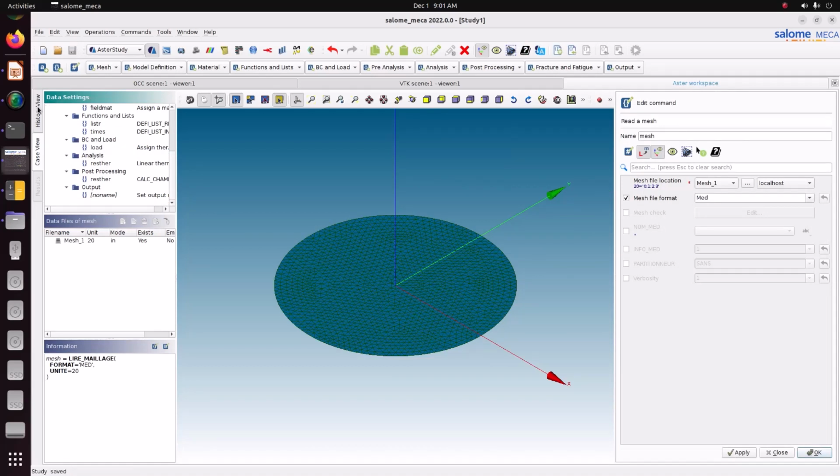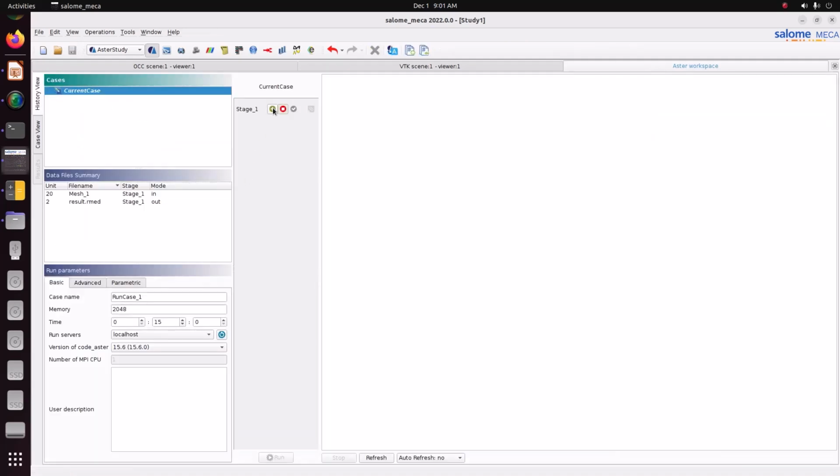We'll run the case. So first you just click this plus button. Just specify some more memory because it is a transient. It has to solve 2700 time steps. I'm specifying some more memory. Time period also I'm specifying, so 50. It will not take that much time. Anyway, I'm just specifying this. Just make it into 5 seconds. Just run it.